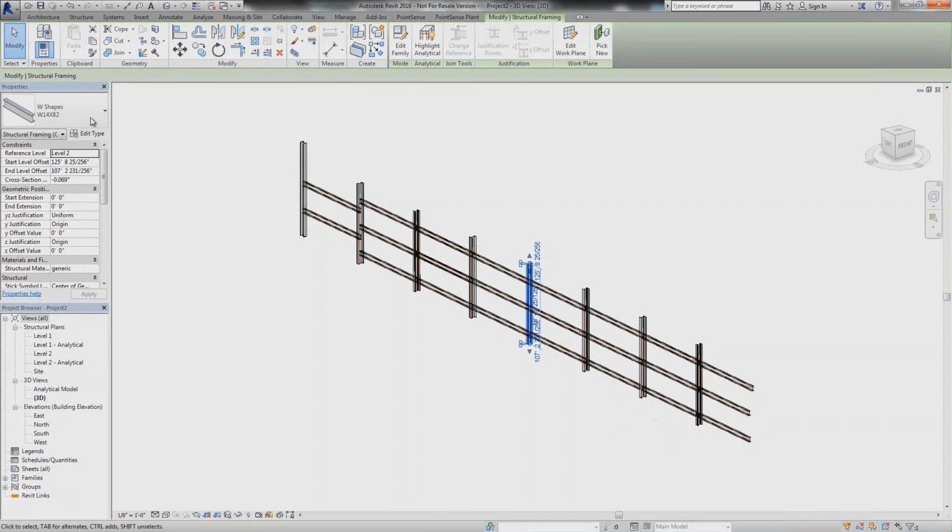Right, and there's actually a good video up on that YouTube channel showing how we use the planar analysis tool to extract only the ground points, then convert those ground points to a Civil 3D digital terrain model. So you can do that as well, and you could extract ground points, but like John said, you can use that same tool on wall faces and other objects as well.